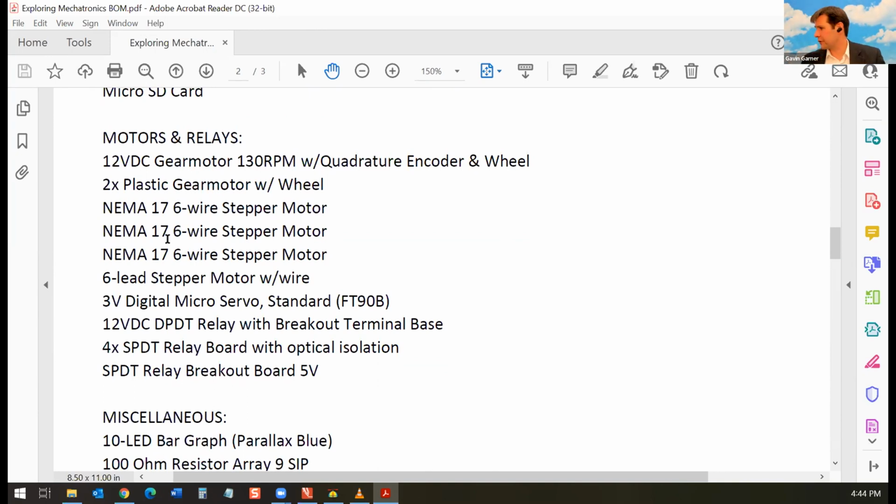What I've been using in my course are these little yellow plastic gear motors, and they are the absolute cheapest motor you could possibly imagine. But with some mechatronics, we're actually able to get them to work pretty well. So I have the students right now for Friday working on building a servo system out of these little cheap gearhead motors, where they've got a homemade quadrature encoder system and then a proportional controller that lets them work pretty well. And then of course we'll cover RC servo motors and stepper motors.